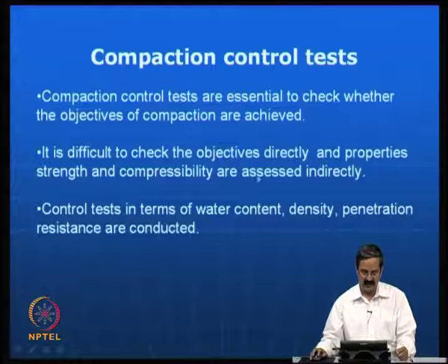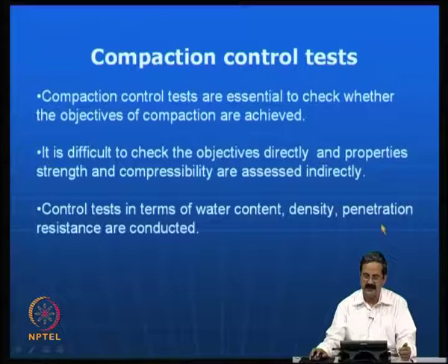So, one should be very careful with that type of soil. So, control tests in terms of water content, density and penetration resistance, we will see that, say for example, penetration tests are also done to check the suitability of soils as compacted and to see that the field compaction is done properly.